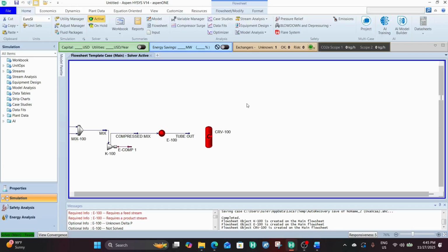If you can remember, for the electrolyzer, we did not specify any reaction. We already had the inbuilt reaction because of the electrolyte wizard that we had. So the electrolyte wizard generated the electrolysis reaction. But here we do not have an electrolyte wizard because we are working with the normal Aspen Hysys properties, not the Aspen properties. So we need to specify a reaction.